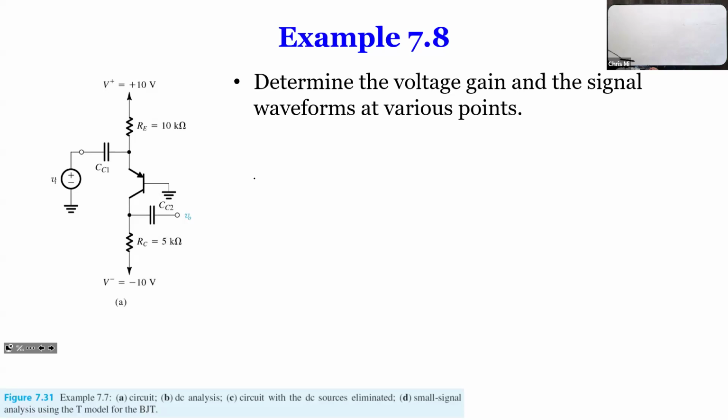The only thing you pay attention to is that when you draw the circuit, it flips D and S, or C and E. Of course, the current direction also changes. Remember, for NPN, the current goes into the base, but for PNP, the current goes out of the base. That's the difference.